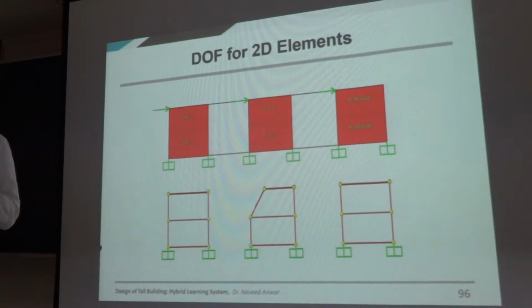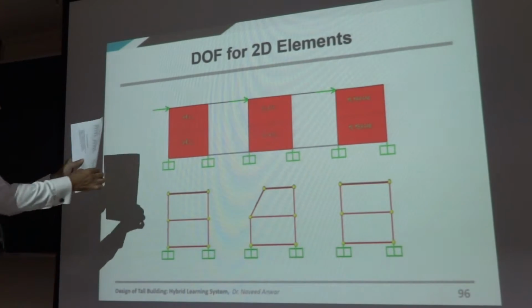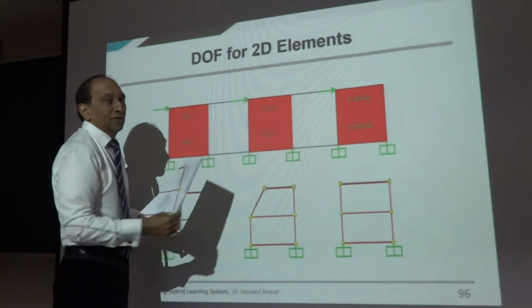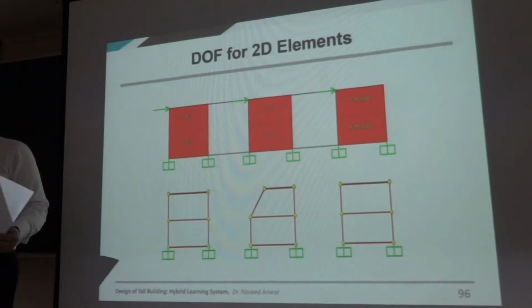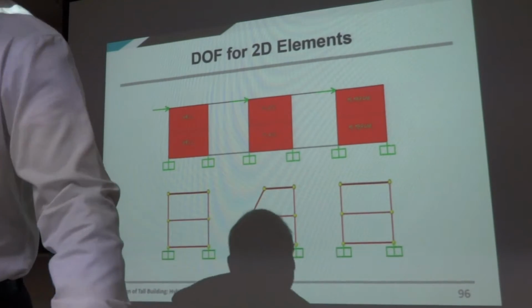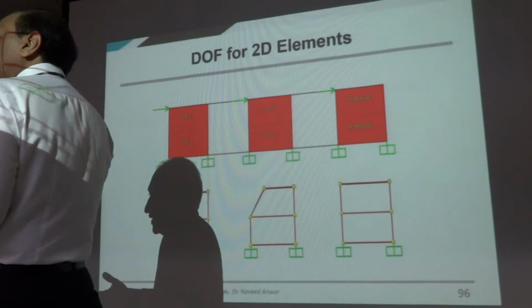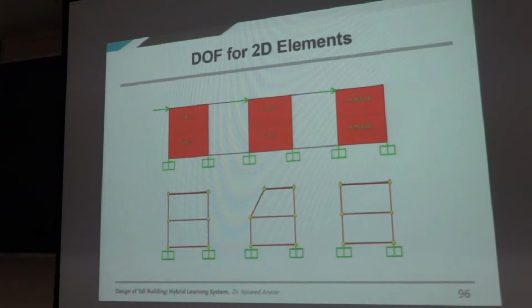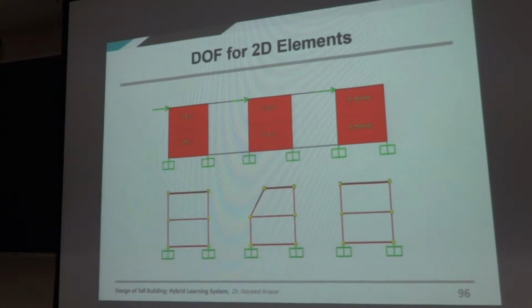So for in-plane loads, shear wall, plate, shell and membrane will be most okay. Shell of course will be okay all the time, but membrane will be just fine. For out of plane loading, plate and shell will work, membrane will not work. Clear?